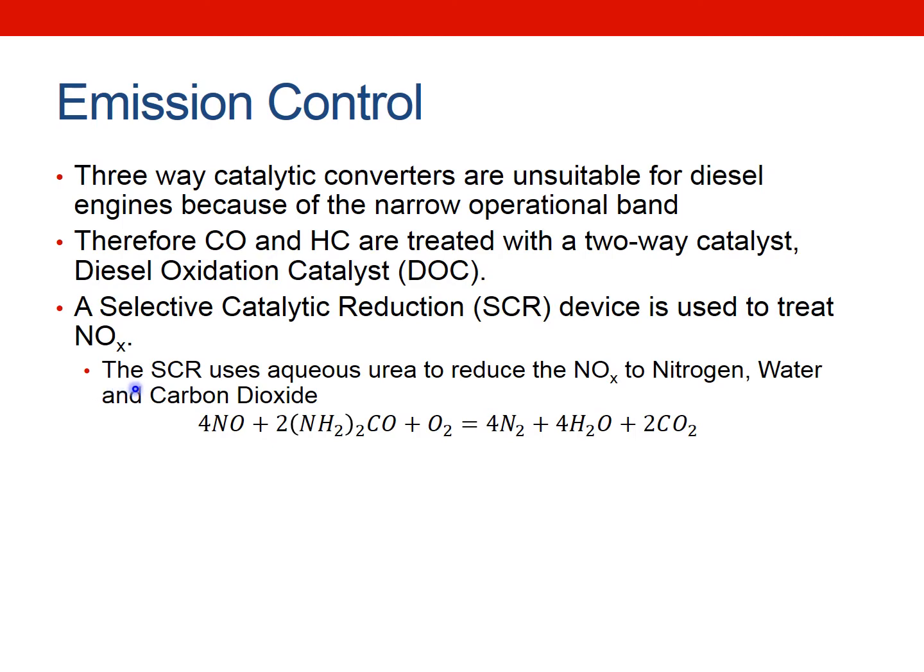So the SCR uses aqueous urea to reduce the NOx to nitrogen, water and carbon dioxide. So this is a formula for it. You have nitrogen oxide plus your urea solution plus oxygen gives you your products, your nitrogen, water and carbon dioxide.